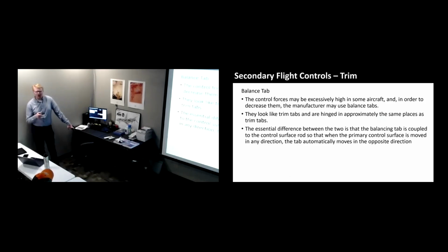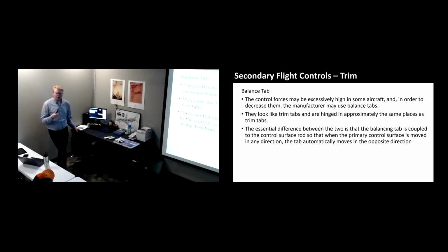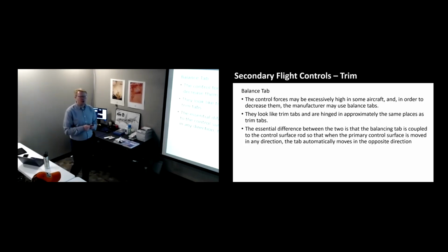But we're not always the only one as a pilot making an input in the elevator. It can also be an autopilot trimmed input. Most autopilots have a little servo, a little motor that moves and can adjust the trim for you. Some do, some don't. Not the most critical thing. Whether you move it or a little electrical motor connected to the autopilot moves it, it's still moving, still doing the same aerodynamic purpose.